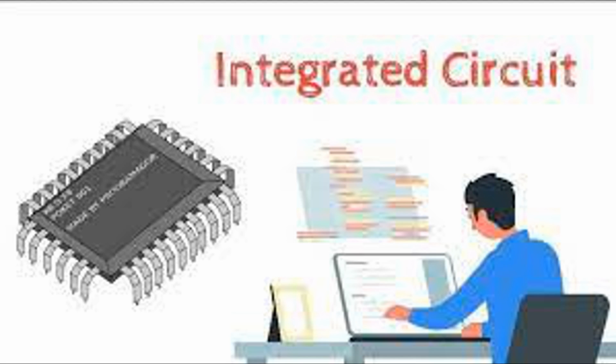Boolean algebra. Combinational logic circuits are often designed using Boolean algebra, a mathematical framework for expressing and manipulating binary values, 0 and 1, and logical operations: AND, OR, NOT, etc. Boolean expressions are used to describe the behavior of combinational logic circuits. Basic building blocks. Combinational logic circuits are typically built using basic logic gates, such as AND, OR, NOT, XOR, NAND, NOR, and XNOR gates. These gates are used to implement various logical and arithmetic functions.